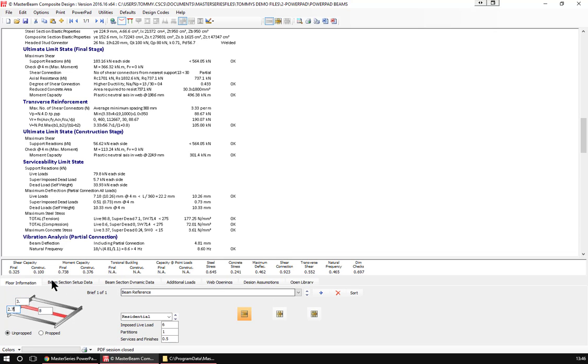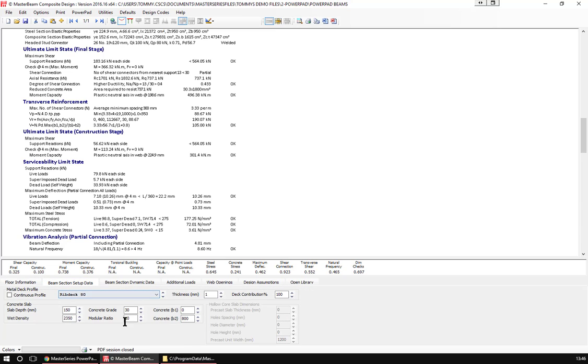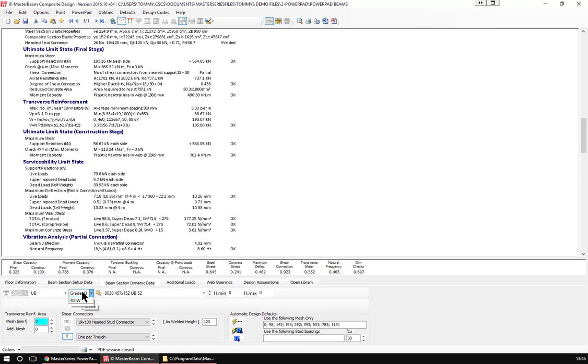And of course we have the options to give you, and it's using RibDeck 80, and we're going to go for grade 355, and I am just going to go and say you design it, and it's coming up with a 305 by 127 48 as the shallowest.